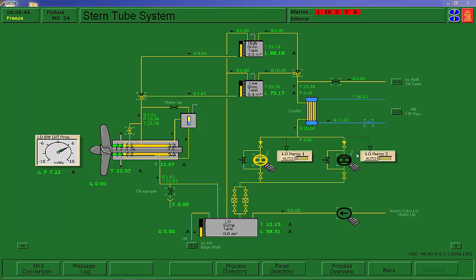On a modern 980 millimeter bore, slow-speed engine, we're talking about a cylinder that's a meter around, and your indicator cock is quite small. You would not want to discover that there's water in the engine when you're rolling it over on air. By turning it over on the jacking gear, you observe the indicator cocks and make sure that water does not come out of any of these, because that's a showstopper.